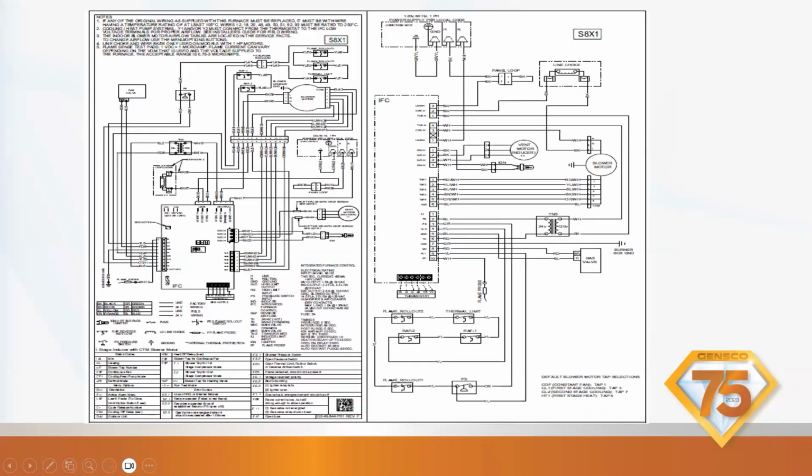Sometimes you're going to see it like this. You're going to see the ladder schematic and the pictorial schematic side by side. And this is really helpful. I think this is the best. This is ideal when we see them side by side like this, because you can see where they are laid out in the furnace. Then you can look over without having to change pages or find another schematic, and you can see what they go to next, how they connect.